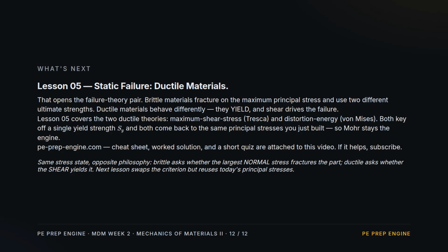Next up, Lesson 5, Static Failure of Ductile Materials. That opens the pair. Today, brittle materials fractured on the maximum principal stress and used two different ultimate strengths. Ductile materials yield instead, and shear drives the failure. Lesson 5 covers the two ductile theories: maximum shear stress, or Tresca, and distortion energy, or von Mises, both keyed to a single yield strength, and both built on the very principal stresses you just found.